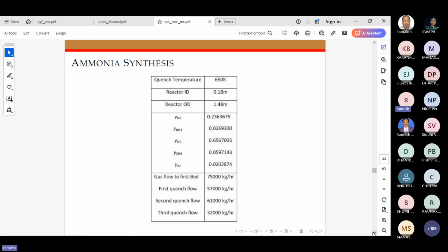So for each set of values of these parameters, we need to simulate the entire reactor operation so that we can finally get a fitness function value. So this is what is done here. And if your population has, say, 10, 20, etc. Remember, in this case, the objective function consists of three variables here, because the three variables are the three mass flow rates of the quench flows.